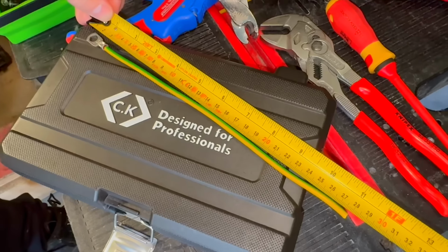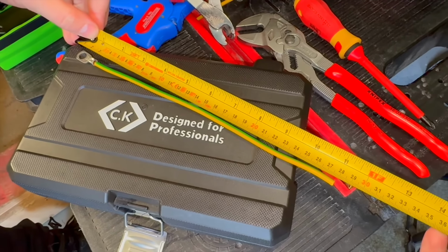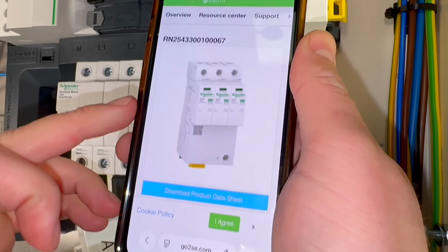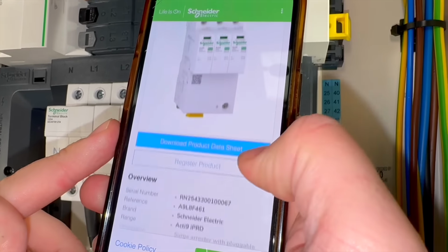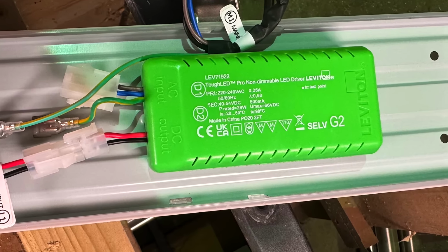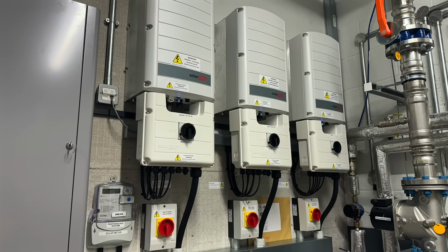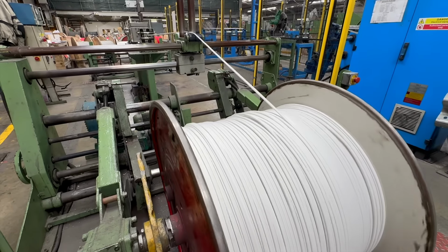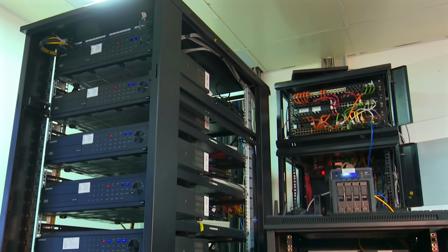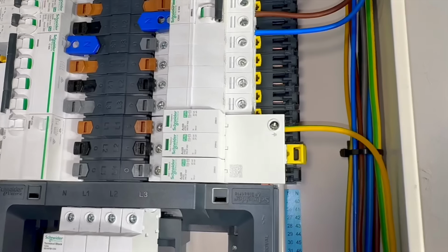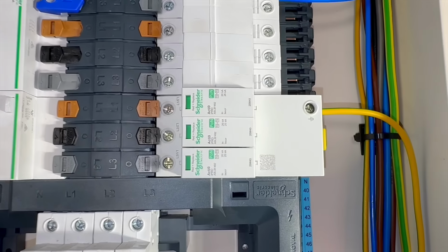This removes reliance on cable impedance between separate devices and simplifies designs in locations where multiple sensitive loads are installed close to the distribution board. So in a plant room where you might find a fire alarm panel, a solar inverter, PLCs, motor drives and networking equipment all supplied from the same board, a combined Type 2 and Type 3 device can be an appropriate solution. Regulation